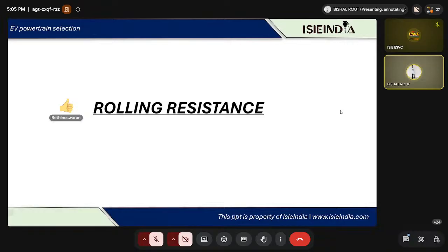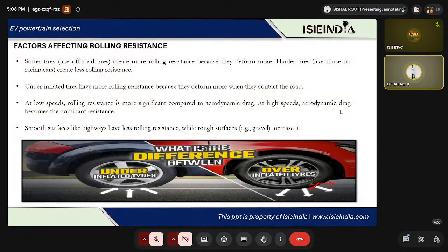because see, when you are going in the front side, let us suppose you are moving in this side, right? If you're moving in this side, this part is getting compressed and this part is getting decompressed. So the forward part is getting compressed and the rear part is getting decompressed. So here you can find a maximum force and here you can find a minimum force. That's why the overall force is going to shift to the forward side of the vehicle, right?